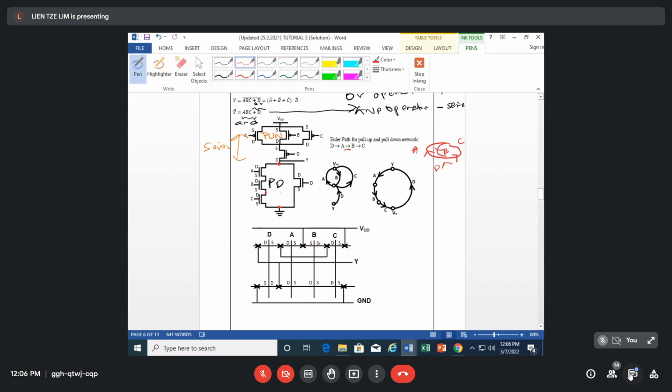Okay, we can label the other terminals as well subsequently. This is drain, and this is source. How do we know this is source? We have to refer back here. The drain terminal of the transistor with input A is connected to the source of the transistor with input D. So this is D.